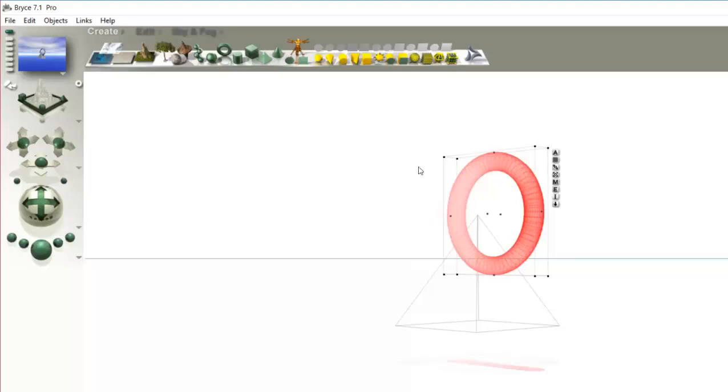And now I'm going to show you a really cool little trick. I'm going to select the torus, which is already selected, but I want to use a tool called multi-replicate. This will give you some nice little variations to this torus that I'm adding. What I'm going to do here is Control Duplicate. I'm going to make a copy of this, but it's going to be in the same spot.